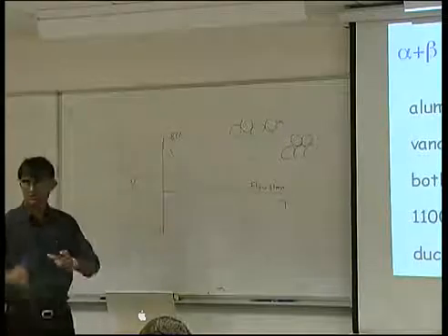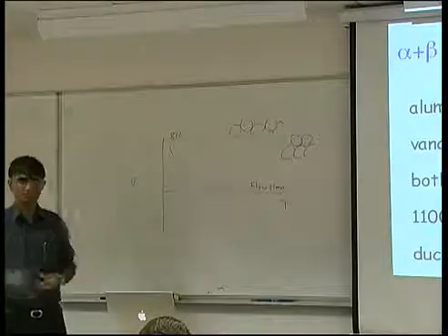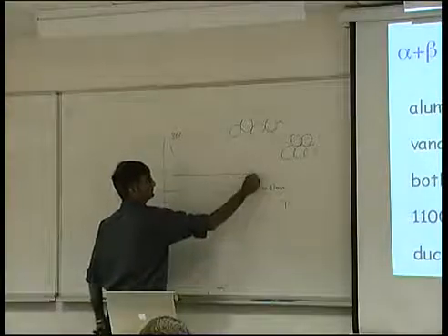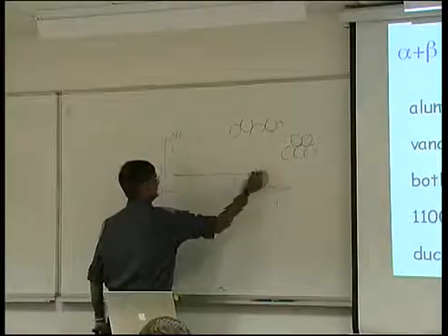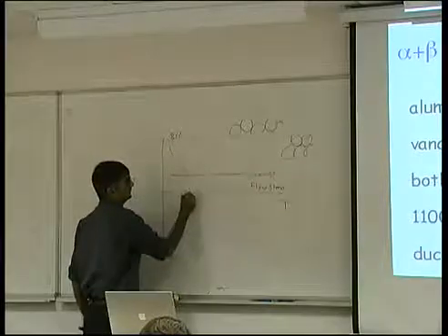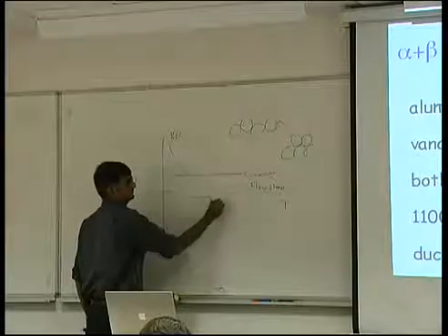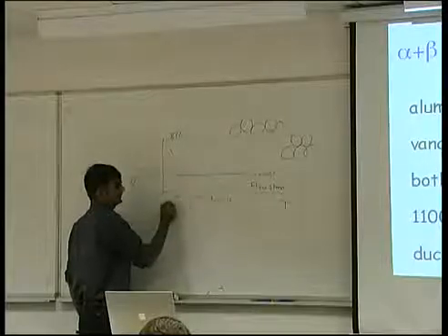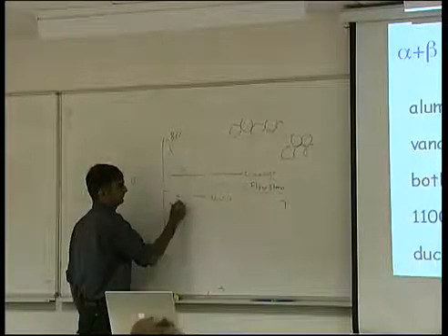On the other hand, the cleavage stress, that means to rip the atoms apart, is temperature insensitive. And therefore, above this temperature, you have ductile deformation, and below this temperature, you have brittle failure.